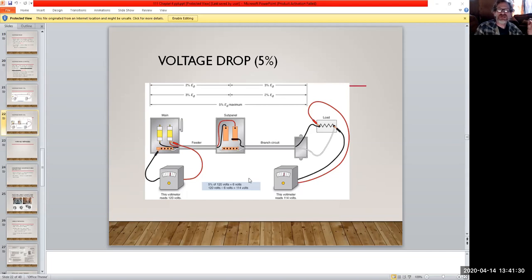And in this case, you got a sub panel, and where you would see something like that is your AC condenser that's outside, right? So you have a main circuit breaker back in the panel for the AC, but then it's got a feed out to, I don't know, wherever in the back of the house or the side of the house. You'll have a sub panel located there, and that could have circuit breakers or fuses, but it's got to be a type where you can see your disconnect, typically, when you're doing something like that, right?